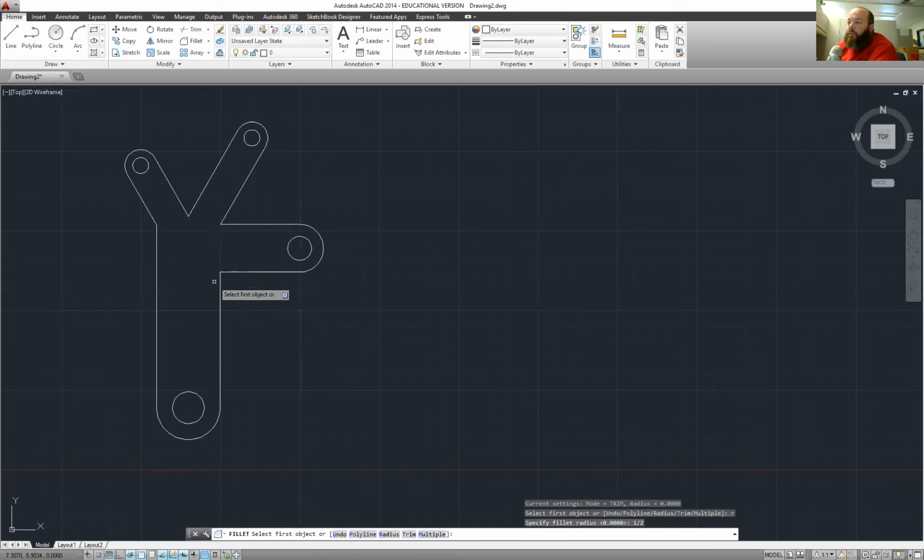Now for this function, we're just going to click the lines that we want the radius to happen on, and it will do it. After it does one, it's going to reset to a standard cursor there, no function. I'm going to hit enter again. It'll give you the radius. You've already set the dimension. So now you just go through and you radius your part here. Okay. All right. Now we've completed drawing one.